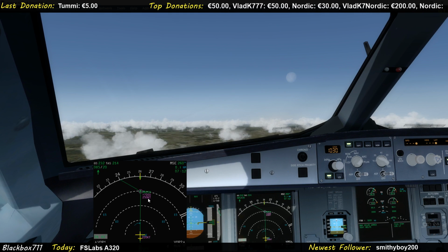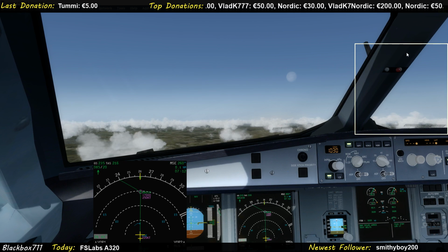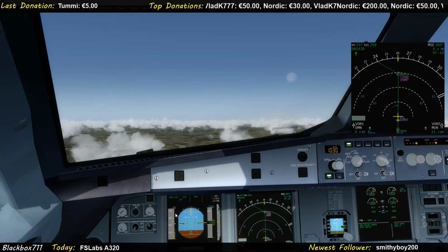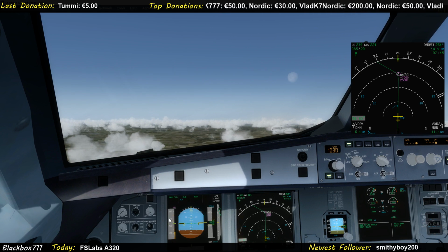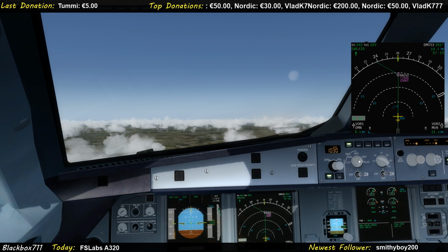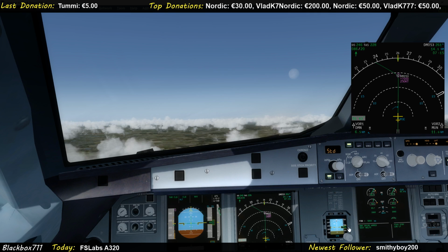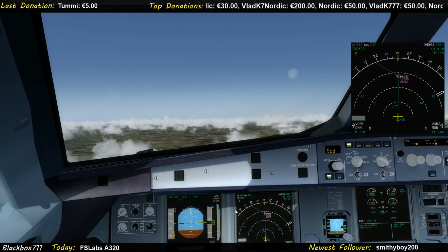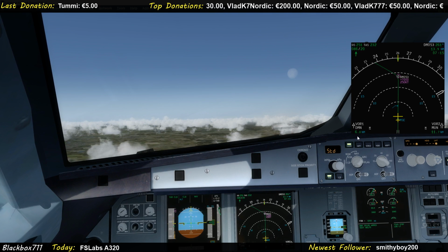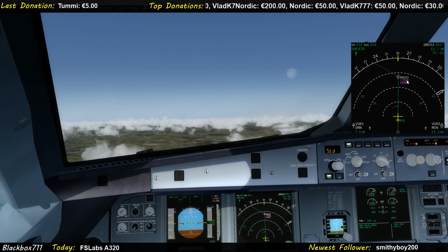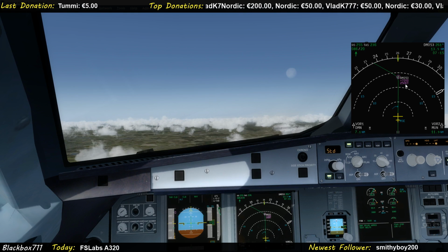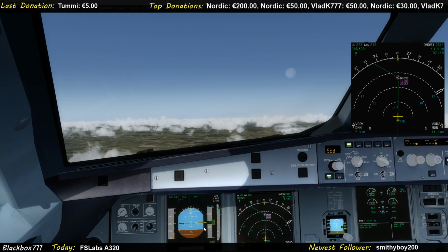First restriction, 220 knots. And so now we've passed that point, the FMS will command automatically 250, which is very nice. We're passing transition, setting standard. Standard level 49er. Next restriction, Delta Mike 053 at 70 or above. Should be no problem.